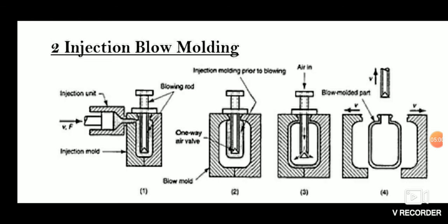The cavity mold forms the external shape and is clamped around a core rod, which forms the internal shape of the preform. The preform consists of a fully formed bottle or jar neck with a thick tube of polymer attached. It will form a body similar in appearance to a test tube with a threaded neck. The preform mold opens.